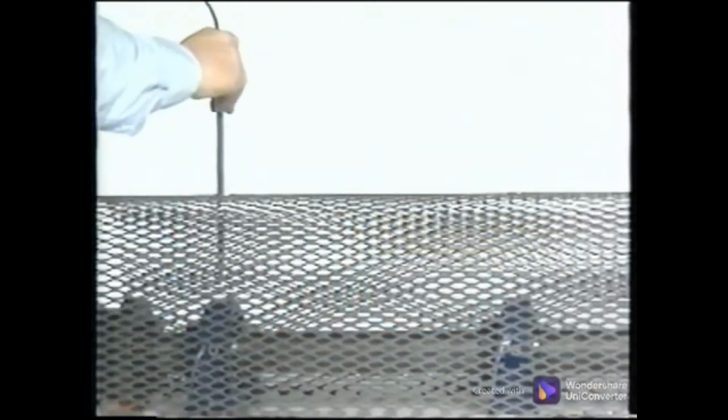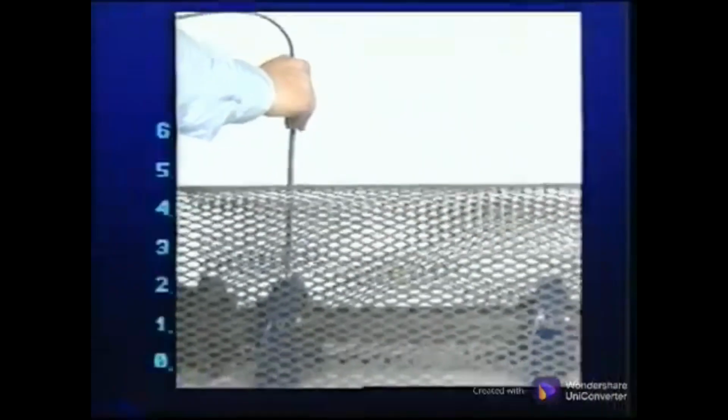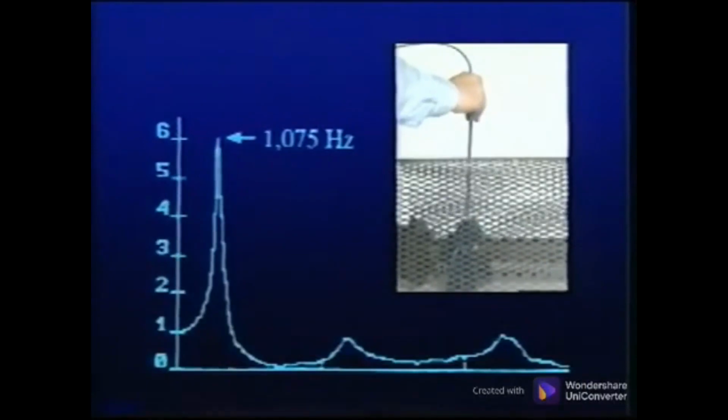This long stinger or probe is useful for reaching hard-to-get places and for reaching through a mesh guard to a bearing. However, this probe should not be used for general points because of the amplitude inaccuracies beyond its resonant frequency, which is approximately 300 Hz. Since many problems you want to detect occur outside this frequency range, it is not the ideal tool to be used with a sensor.